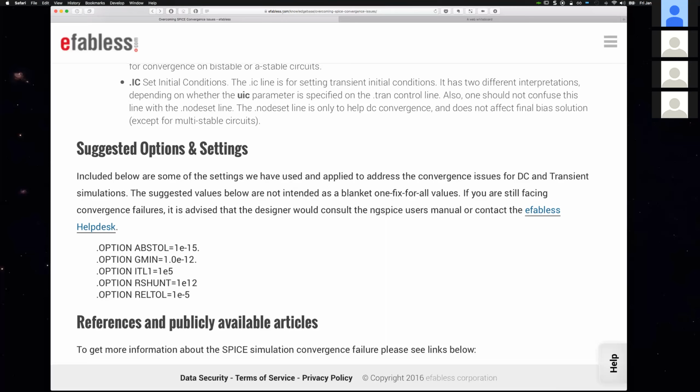If you submitted it and the remote ACE continued to say that something was failing because it wouldn't converge, I would allow the challenge to be submitted with the error as long as you had a simulation to show that it does pass. If you can make it pass with a particular value of reltol, then it's very easy for me to tweak the test bench to add that value. So that would be my recommendation for the first attempt to get something to converge: use reltol.